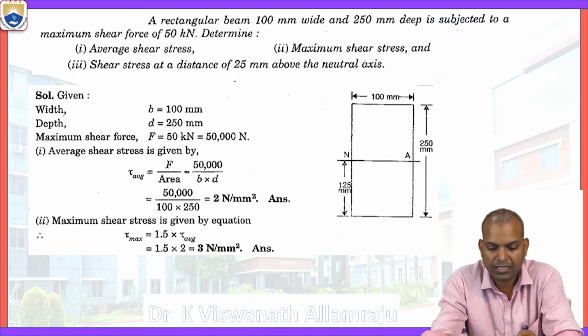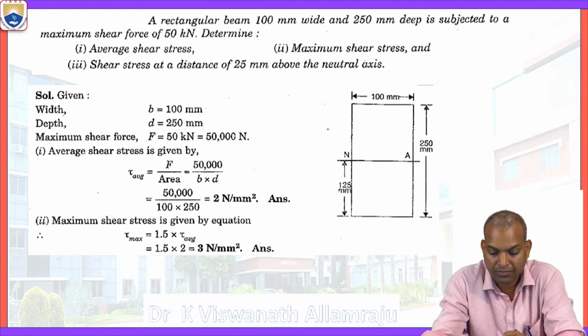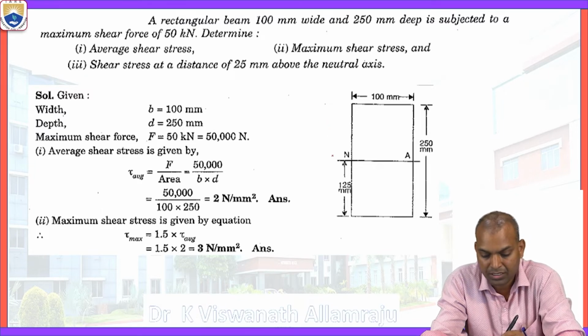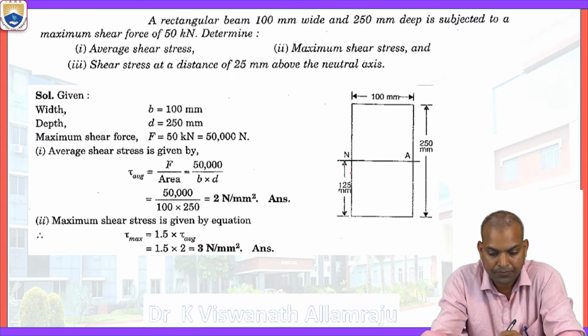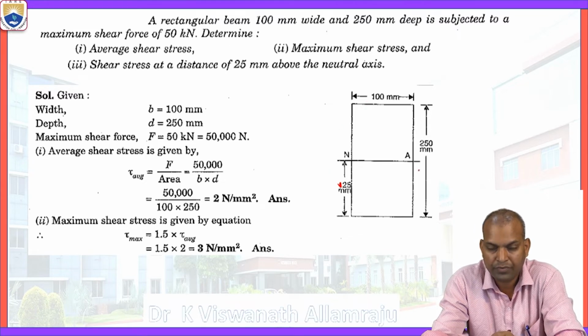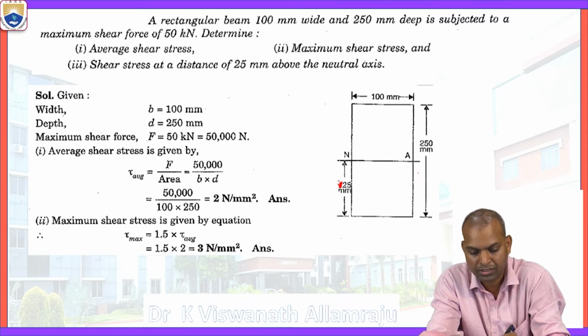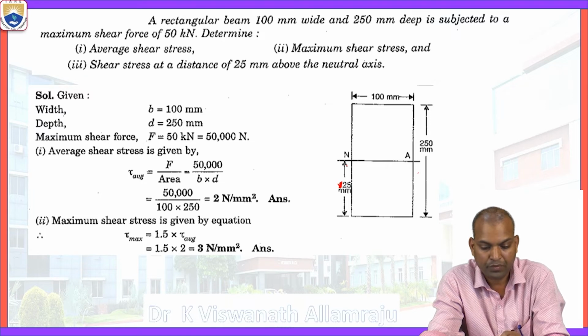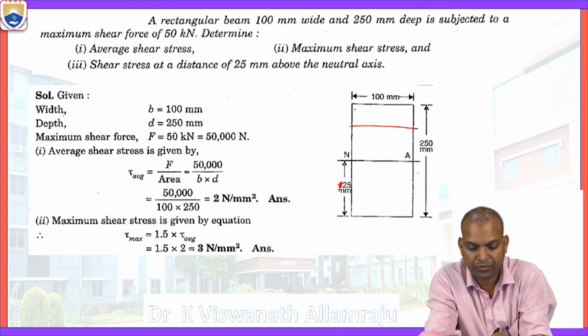Now from this data we can draw the figure. It is 100 millimeters wide and 250 millimeters deep, and we need the shear stress. The top edge is 125 millimeters above the neutral axis, but we want the stress at a distance of 25 millimeters.